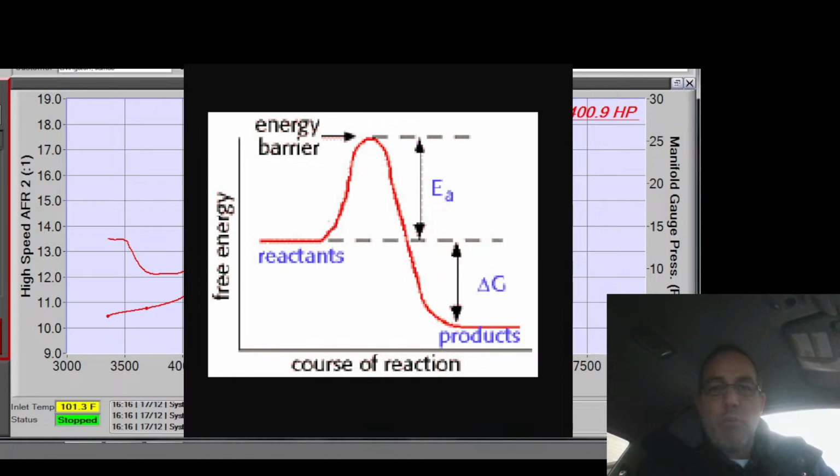Well, this energy can be thermal. It's more often going to be thermal. But pressure is part of that. As you raise cylinder pressure, we're adding energy to it, which could be considered thermal, because usually as you compress things, they heat up. So I have that, and I have flame happening in the chamber. So I have heat being added to the chamber, and I have pressure being added to the chamber. And if I have my cylinder head, let's say you've got one hot spot somewhere in it, now I have an area, we'll say that before the pressure happens, I'm really close to the activation energy on my head, right up here. I'm really close. I haven't activated it yet.